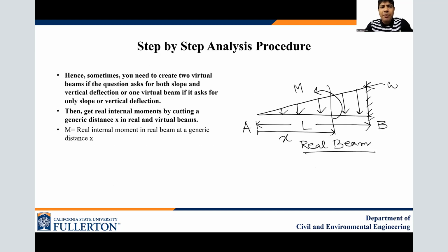So now is our time to go through the step-by-step analysis procedure for the virtual work method. What we need to do is take our real beam and cut at a distance x to find our internal moment, which we call uppercase M, the real beam internal moment.